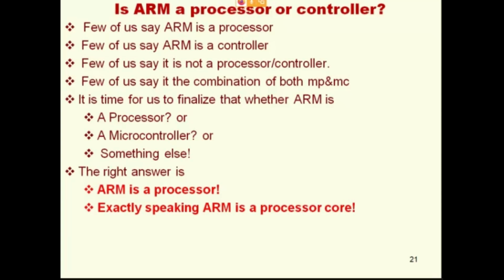There are a lot of microcontroller manufacturers. These manufacturers get the ARM processor core and keep it as the chief minister. That is very important. So ARM is not even selling a microprocessor. They are selling only IP cores. Companies manufacturing microcontrollers get the ARM IP core, add their own peripherals, sell it in the market, and proudly say that their microcontroller has an ARM core inside.